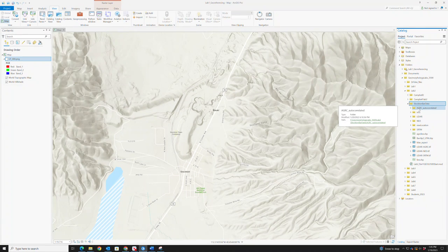The AGRC is from 2007. The LiDAR was, I think, from 2014. The NED is processed from data that was produced before 2004, and the SRTM, I believe, is from the 1990s, like 1998, flown from the space shuttle. The SRTM and the AGRC, because they're coming from radar in one case and air photos in another, bounce off of the data, the reflected light or the radar is bouncing off whatever's on the Earth's surface. So they're not bare Earth models. They would be thought of as a digital surface model of the Earth, not a digital terrain model.